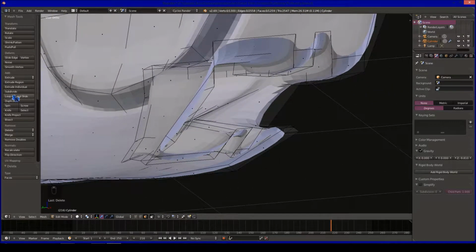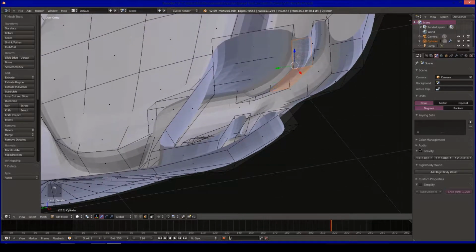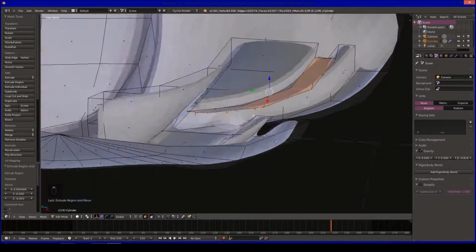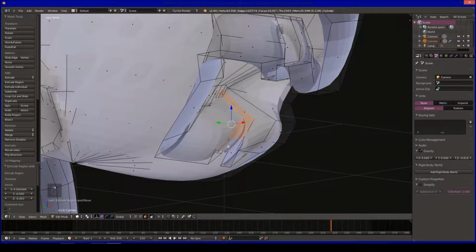One recommendation I do have on the teeth is to make them look a bit more realistic and not quite as rounded. Take the close edge of the teeth, extrude it, take it down just a little bit. What it'll do is tell it to not subdivide nearly as round.